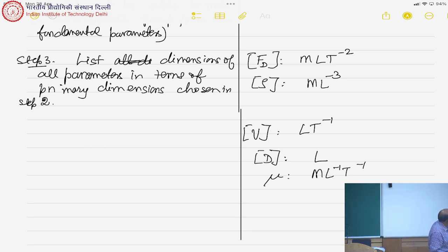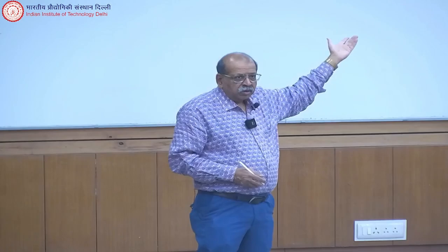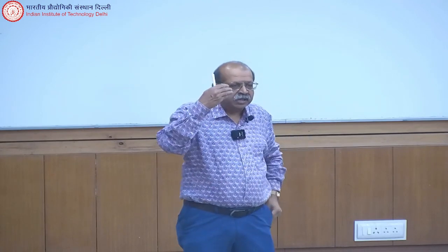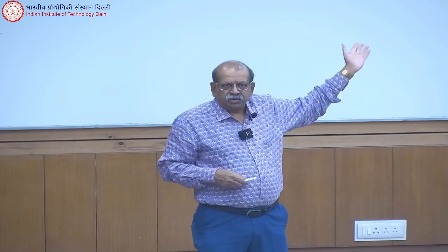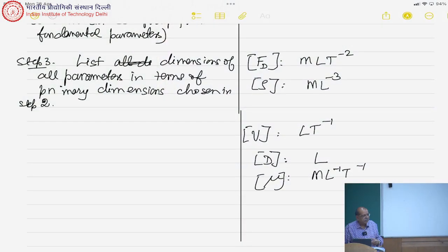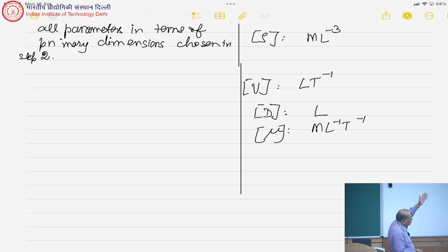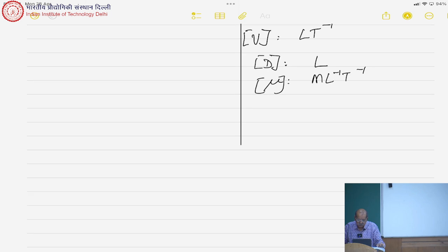Now this is mu, you may have your doubts, but these things you can straight away see. mu times dv by dy is stress. So using that you can easily get this. Or if you know the units of mu, it was Pascal seconds, so from there you can get it. And it's useful to remember these. So at least some of these variables, density, viscosity, they will appear in all the fluid mechanics problems. Of course, I can give you a solid mechanics problem which uses dimensional analysis. So there again, you'll have to do the same thing. The method stays the same. Okay.